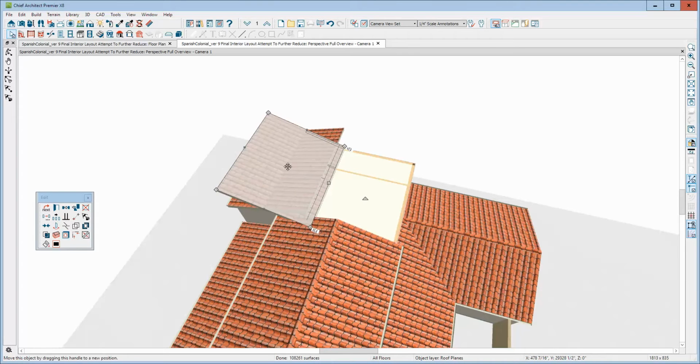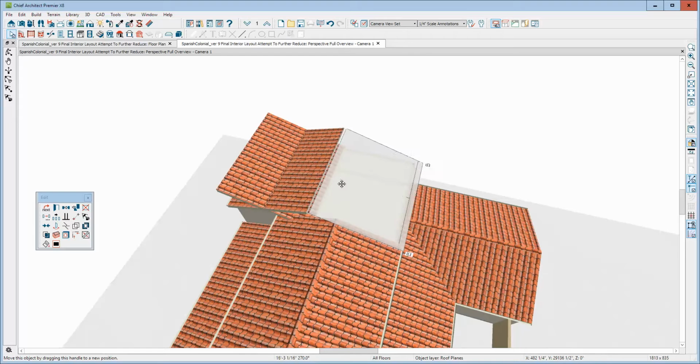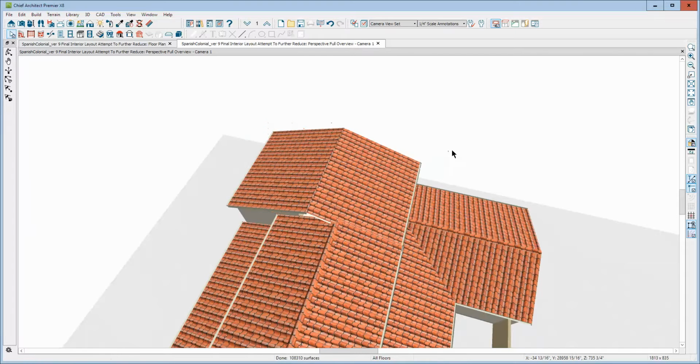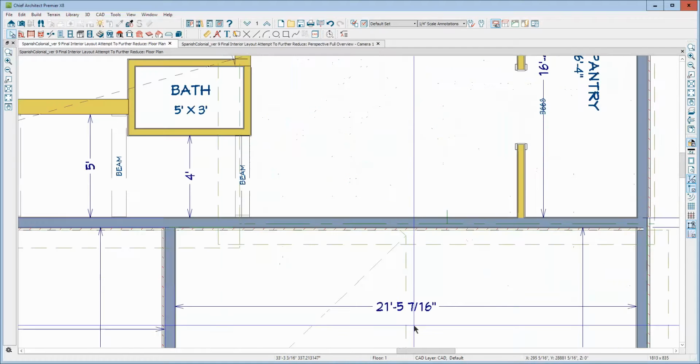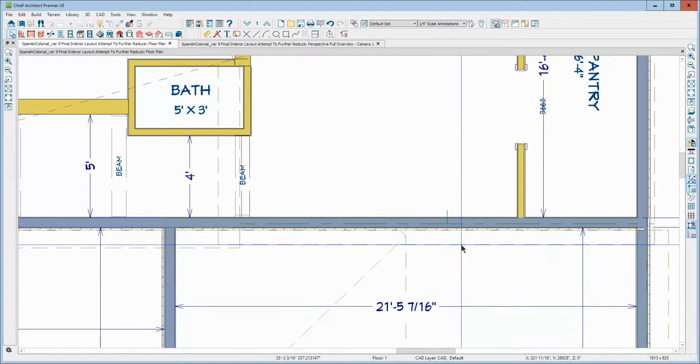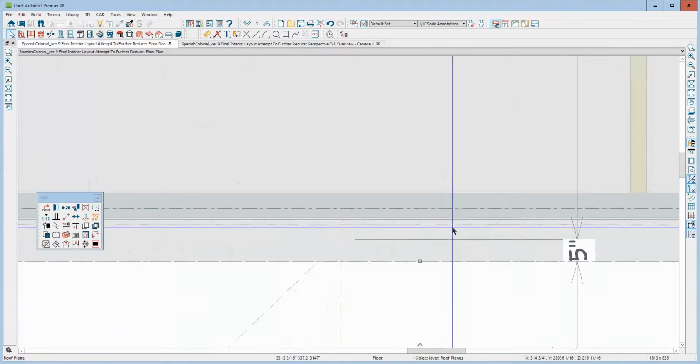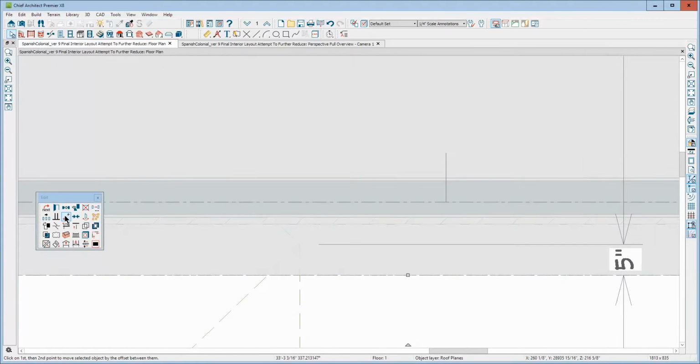We'll move the copy over there. And in plan view, I'm going to set it over this wall. That's something that I just can't do by eyeball in an isometric camera. Like there's that, see, it's off just a little bit, not off very much. We'll move that baseline from there to there.